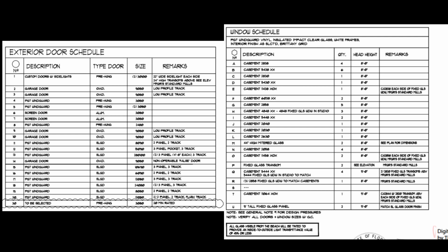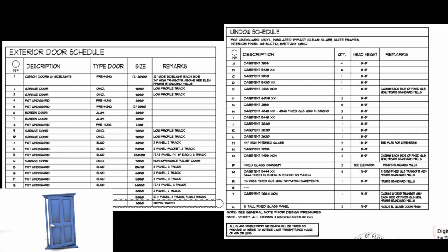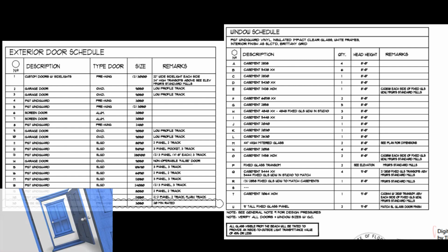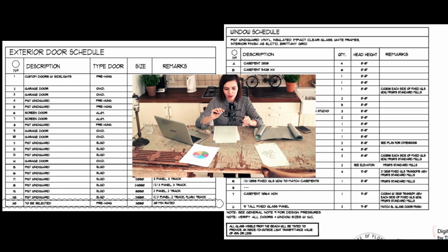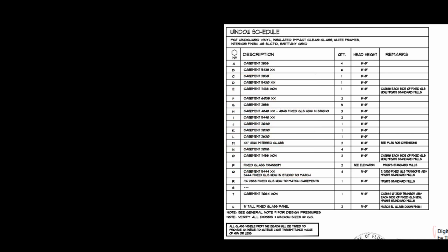Architectural plans can have numerous different schedules. Schedules are charts that have important information. You can see here two schedules: the door schedule and the window schedule. These schedules show a letter or number icon that labels each window or door. It also shows the type and size of a door or window. Schedules can also show quantity of the window, door, or other item being shown. Other common schedules include hardware schedules, finishes schedule, appliance schedules, etc.